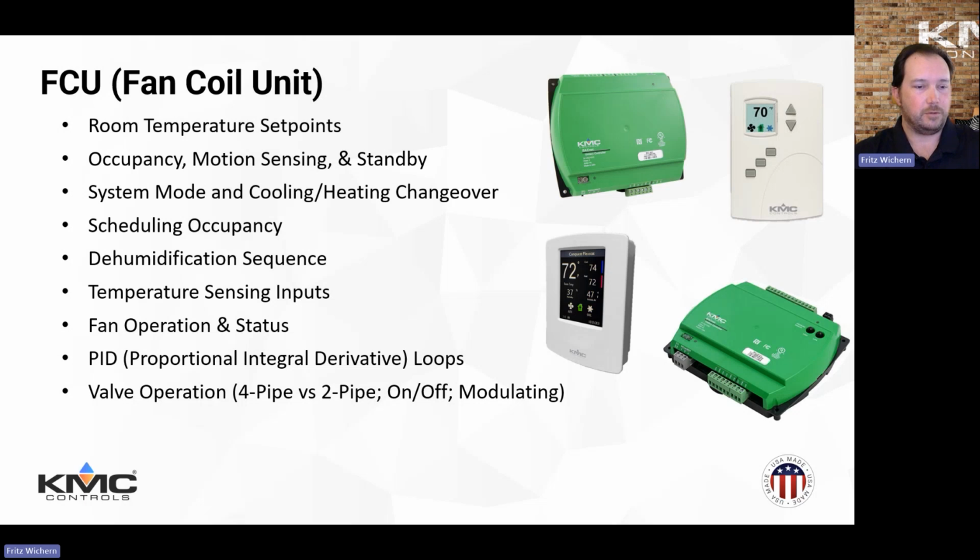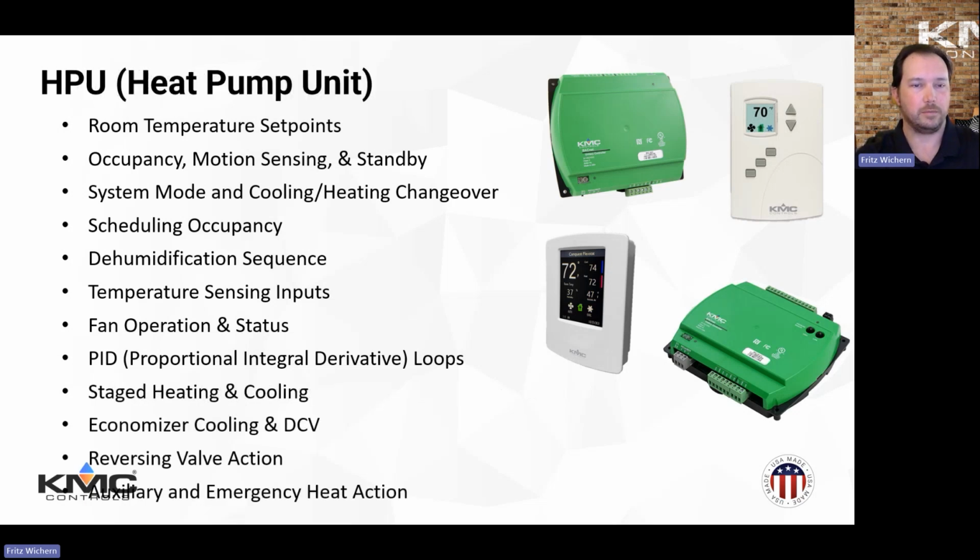So we'll move up next to our heat pump unit. The set points, occupancy, and system mode are all the same. One differentiation with the system mode and changeover is that the changeover doesn't actually take place until after a fan delay. The scheduling occupancy is the same. I don't know if I talked about this before in the fan coil, but this is going to be passed down either from Total Control, or if you've got it tied into a Niagara system, that occupancy command can be passed down and in.